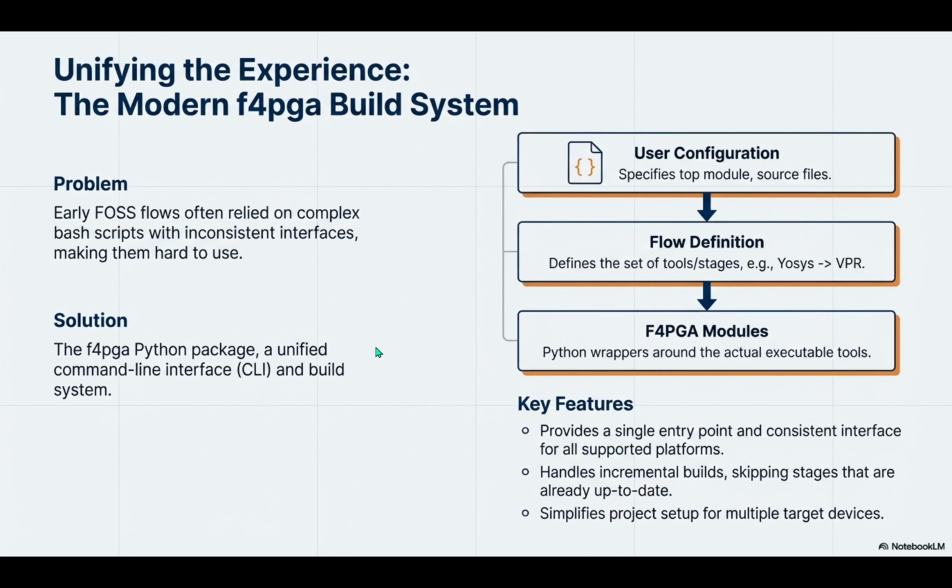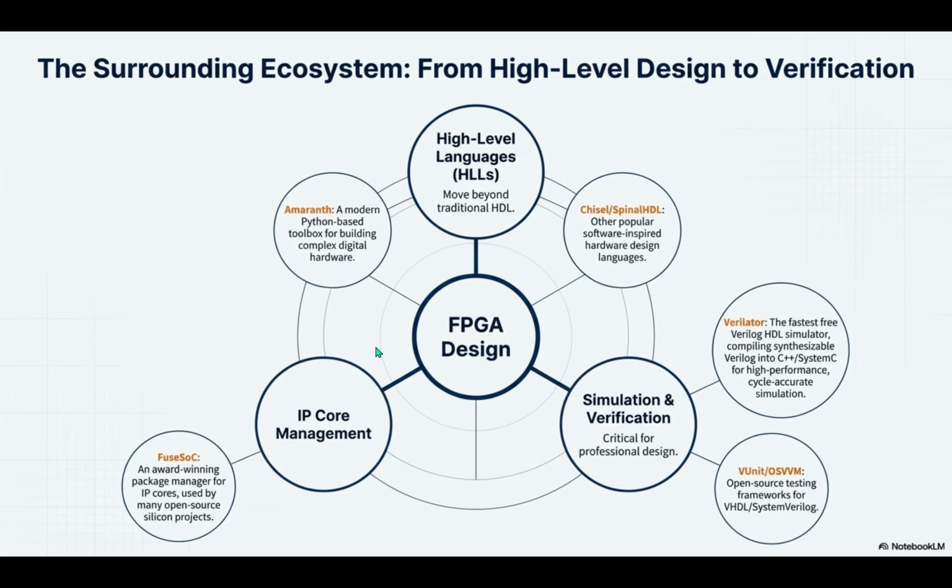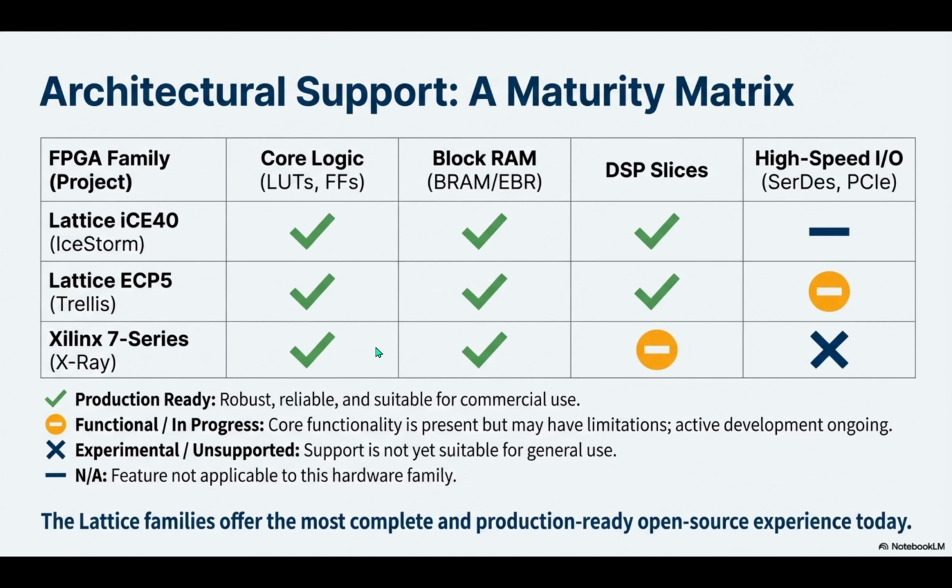They are. When you look at the Xilinx 7 series from Project X-Ray, the reverse engineering is still catching up. High-speed I/O like SerDes, those blocks that handle multi-gigabit data streams or PCIe, they're still marked as experimental or unsupported. Their complexity just makes them exponentially harder to map out. So if your product needs cutting-edge high-speed networking, you're probably still locked in to the proprietary tools for now. For now, yes. But for general computing logic and the majority of embedded applications, the open source path is fully viable today, and the usability is improving dramatically.